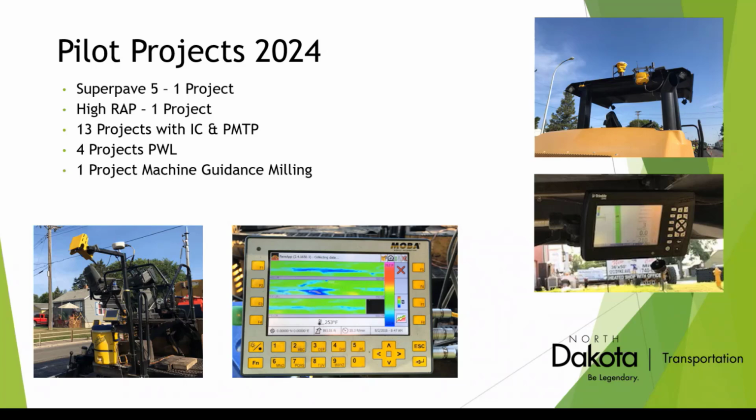If you have a really rough road, 50%, 200 inches per mile to 100 inches per mile is probably the best you're going to do. Well, if you're milling, which more and more we are doing, and micro milling, if you have something that approaches grade and slope control very accurately, your lift thicknesses are going to stay consistent, your yields are going to stay consistent, and your ride and density are going to be much better because you have consistent thickness of mat and consistent slope.